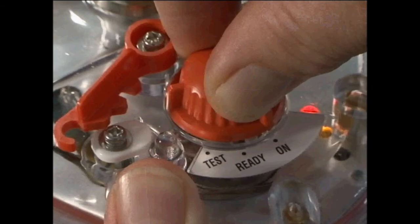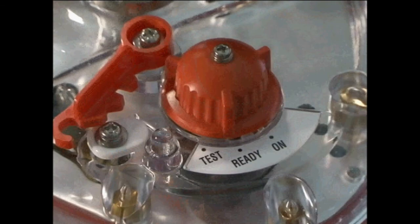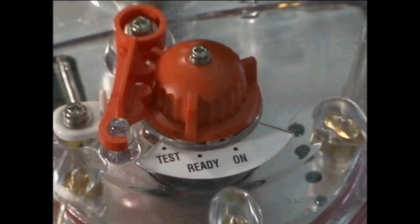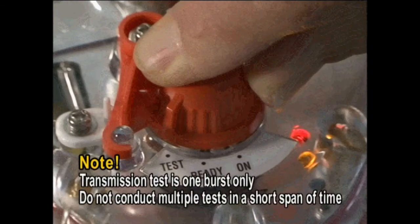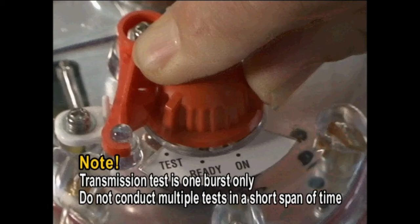The unit will cease transmitting when it's removed from the water and the switch is returned to the ready mode, turning off the power supply. It's necessary to test the EPIRB once a week to confirm that it works properly. Only one transmission burst is permitted during the transmission test. Never attempt to repeat the test.